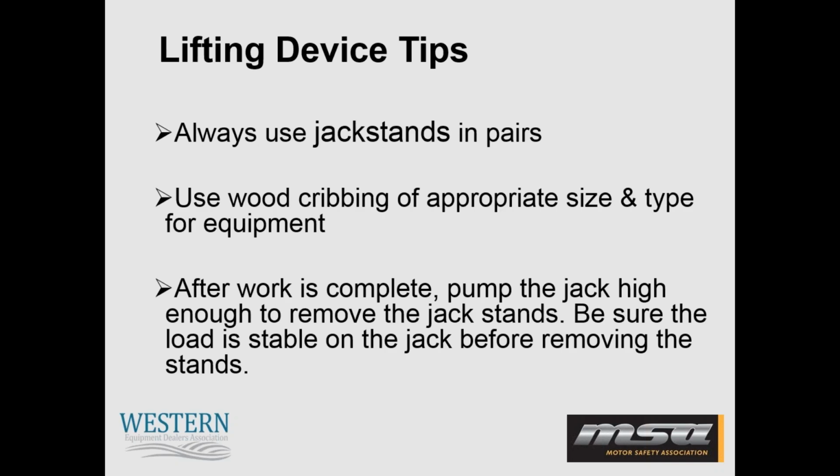Always use your jack stands in pairs. This helps with the stability, opposed to using just one jack stand and trying to balance it in the middle of the piece of equipment you're lifting. Use those jack stands in pairs. And when you are utilizing wood cribbing, make sure it's of the appropriate type of wood so that we are using a hardwood and we are recalling that 3-to-1 ratio as mentioned earlier.